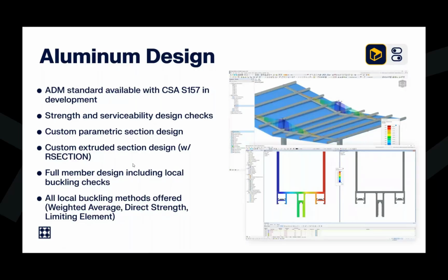Now, as far as local buckling methods offered within the ADM, we offer all three, including weighted average, direct strength, or limiting element.